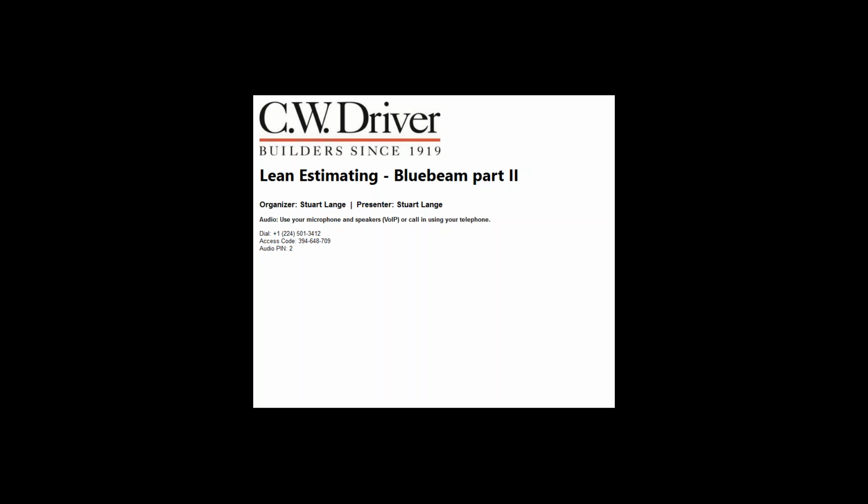Go to a page and zoom over to get a closer look at a sheet where the title block is. Everybody there? Then draw a box around it. It'll give you a little note saying that's what it is. For this example, I'm not going to add words, I'm just going to leave it as a drawing number. We'll say OK. Then I want to do it for all pages, and then I hit OK.